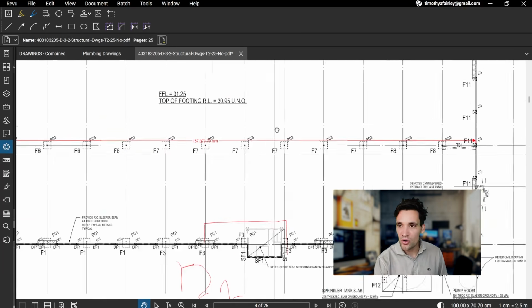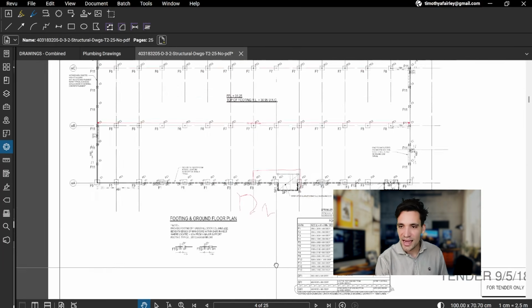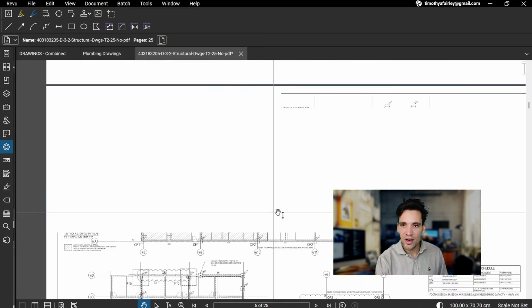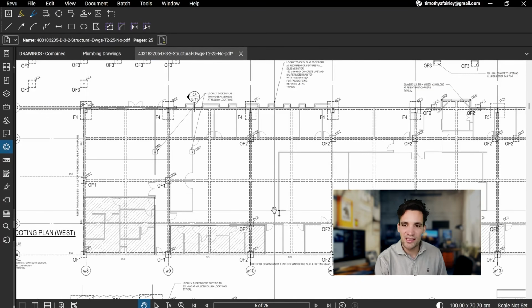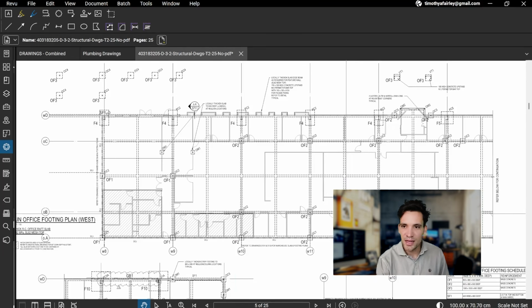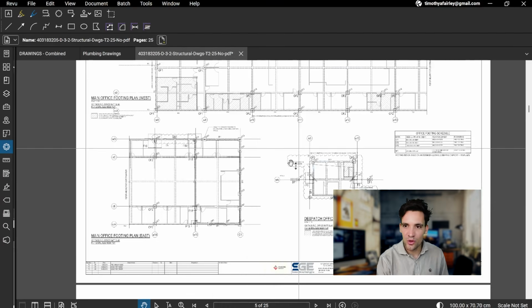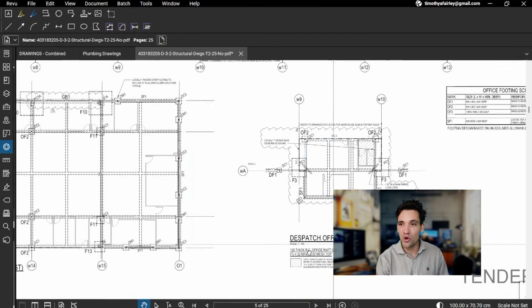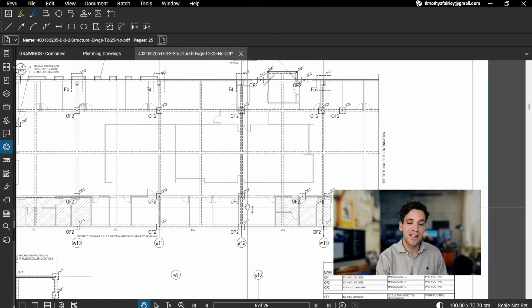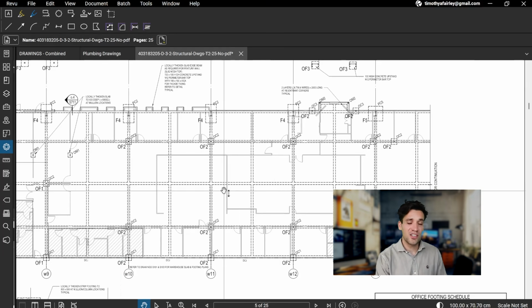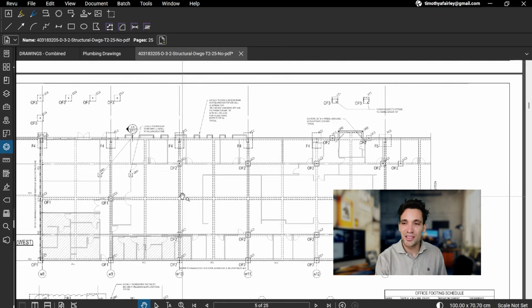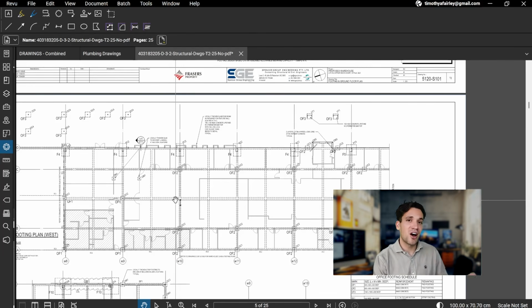So you'll find on every drawing, they actually will call out heights. And what these mean is basically there's different annotations for them, but FFL will be finished floor level. Sometimes they'll just, for example, on earthworks drawings, they often just show the RL on them, which is, I actually don't know what it stands for, but I've never had to know what it stands for. I just know this means what the height is.